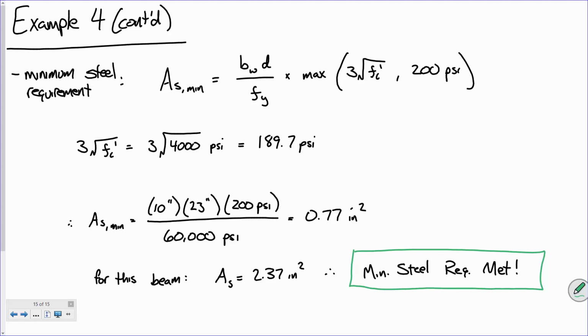Let's say this beam has like 2.4 square inches of steel, right? We met that limit by having 3 number 8s. What if you put 4 number 7s? What I'm saying is later on, what we're going to be after is ensuring that we have enough steel for strength, and there are multiple different ways that we can do that. And there are beam charts we're going to look at later on.